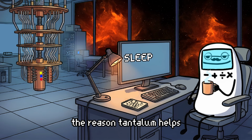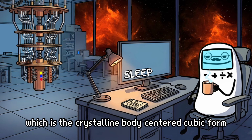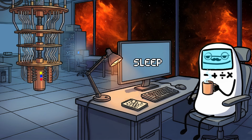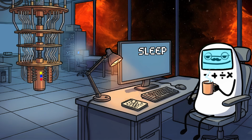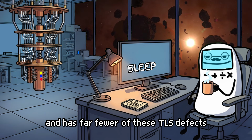The reason tantalum helps is that the alpha phase of tantalum, which is the crystalline body-centered cubic form rather than the tetragonal beta phase, has a surface oxide that forms much more slowly and has far fewer of these TLS defects.